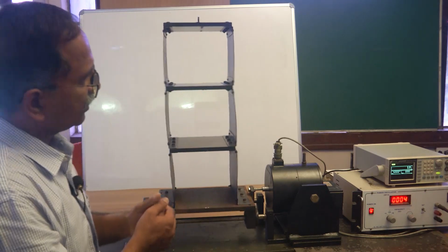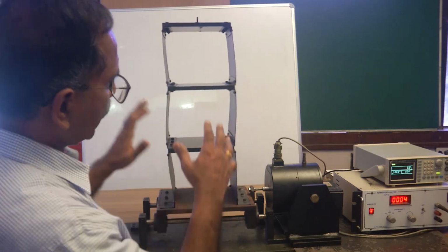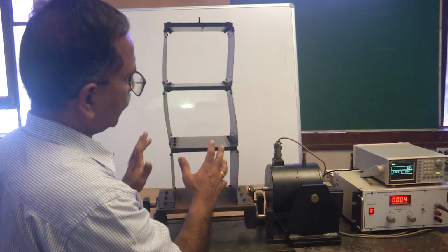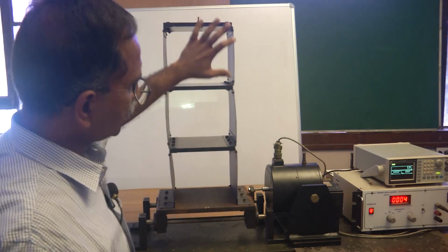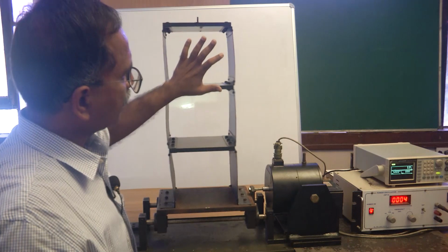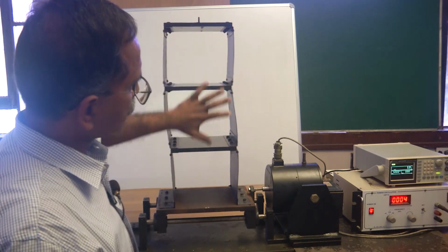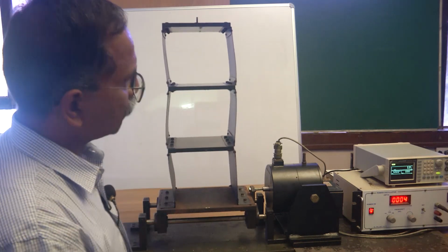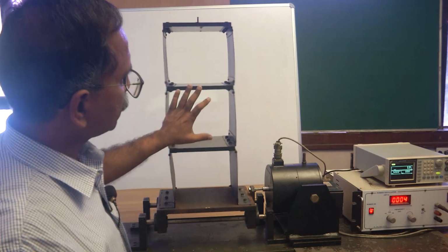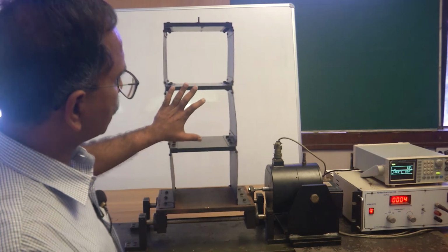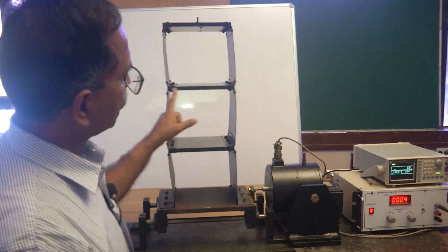So one node gets added in general when you go to a higher mode of vibration. Again, this is a resonance. This is not strictly or theoretically a mode shape, but the operational deflection shape, or the displacement pattern, of this multi-degree of freedom system when it vibrates at its resonance actually represents the mode shape corresponding to that natural frequency. So 5.9 hertz is what we have observed, a major resonance here, the third natural frequency related resonance, and at that resonance this executes the largest amplitude.